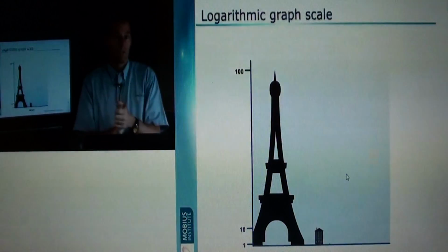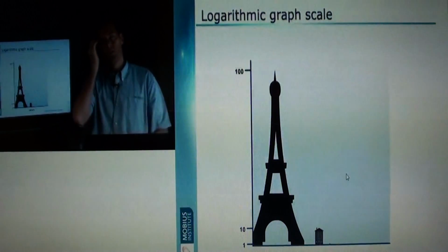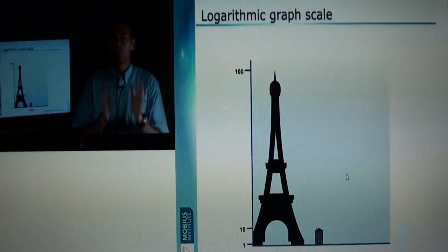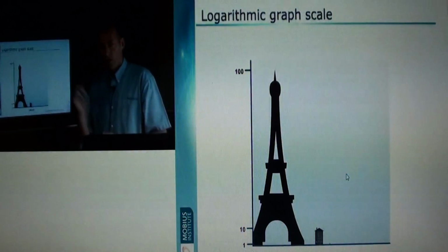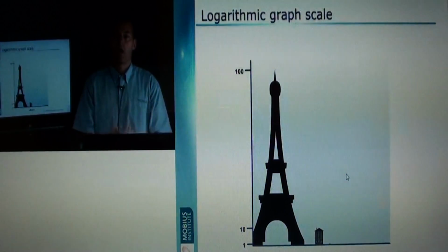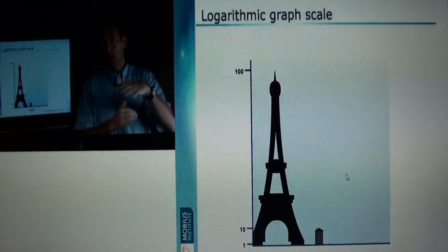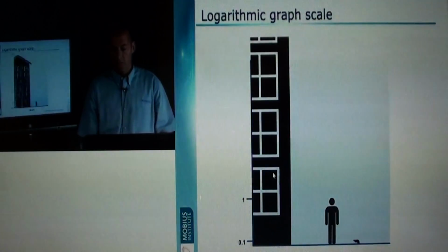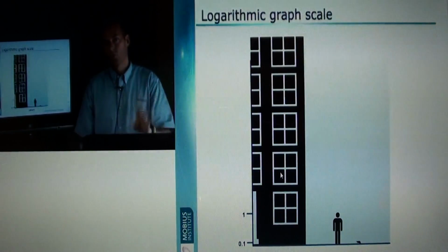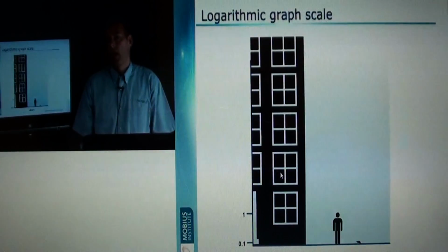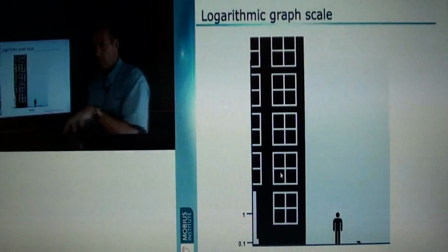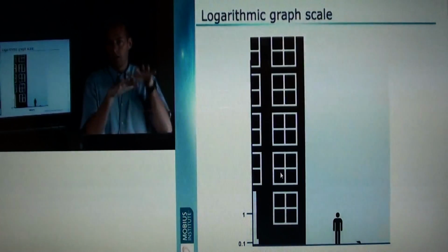If you're fortunate, you might even be sitting there thinking, well, sometimes I can see those bearing frequencies on my linear graph. That's all because you probably don't have the Eiffel Tower in your graph. If there's no big unbalance or misalignment peaks, so your scale is lower, you're looking at this situation perhaps. Now you can see all those things together at the same time. Only when it's convenient that the low vibration is high enough and the high vibration is low enough that you can see it all.